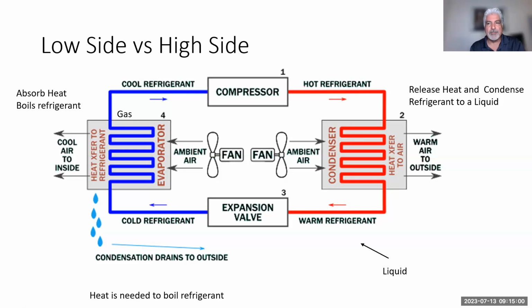If you're going to boil water, when it boils and you see the vapor coming up, you have to understand that it's got heat, and in order for it to stay in a vapor state, it's got to stay warm. But when it cools down, it goes back to a liquid, right? My point is that since the refrigeration system is a sealed assembly, as that refrigerant goes into a gas or a vapor, it's got heat with it. By the time it goes to the condenser, that refrigerant is giving up that heat and condensing itself back into a liquid. So therefore, it is the heat carrier.